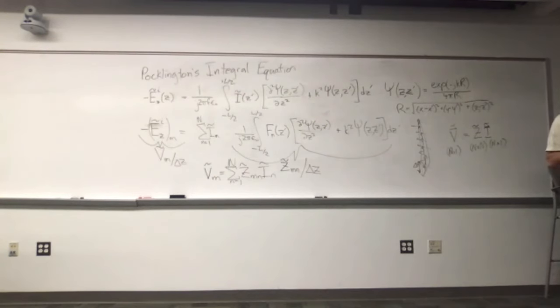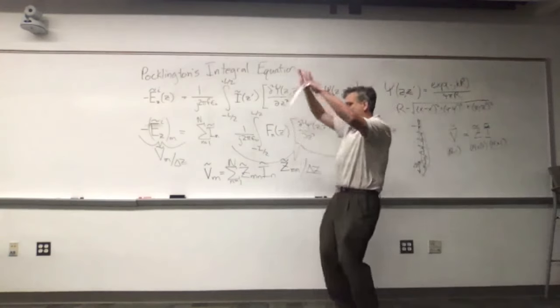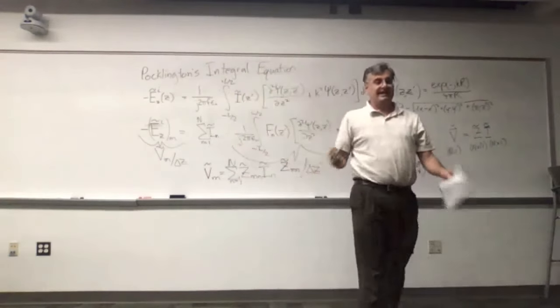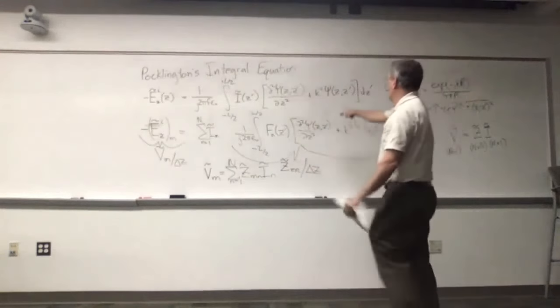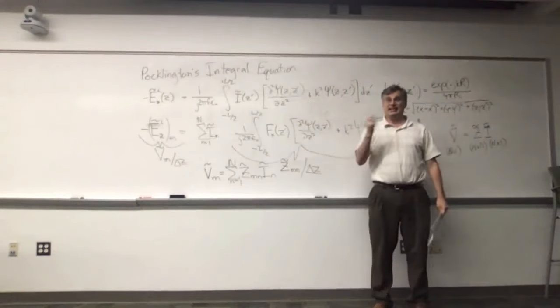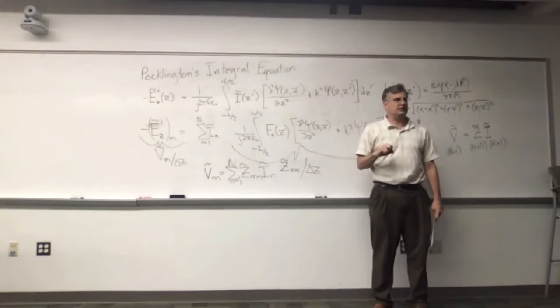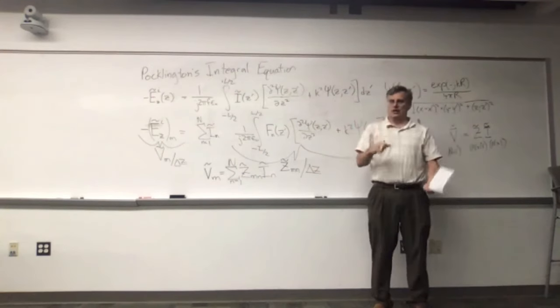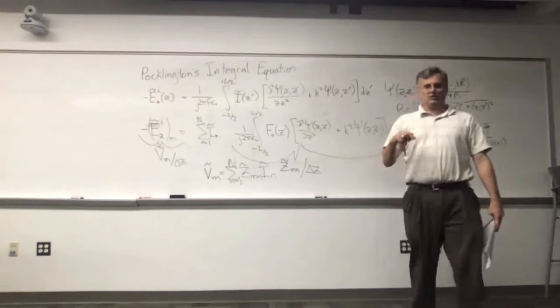And the really cool thing about this system and this way of bookkeeping for the numerical problem is that for a given geometrical system, and keep in mind that I've kind of couched the problem as a sampled wire, there's no reason why you can't modify this technique and make samples of multiple wires, like in a Yagi antenna, or have curved non-Z components of your wire. You can bend your wire around.